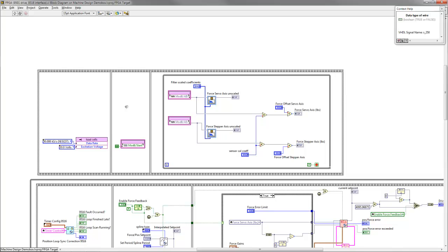If you run in FPGA mode, or onboard axis mode, you'll actually move the position and velocity loops, those high-level control loops, up onto the FPGA, and just run the AKD in torque mode and send torque commands down to it. And that's what I'm doing here with this example.